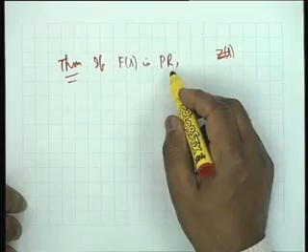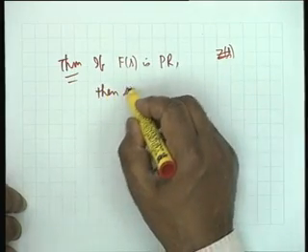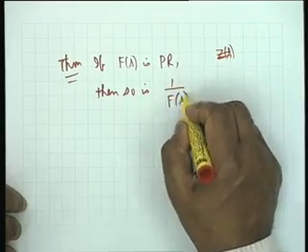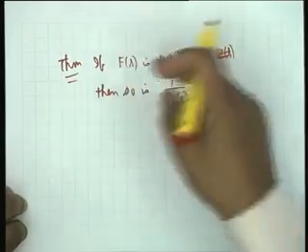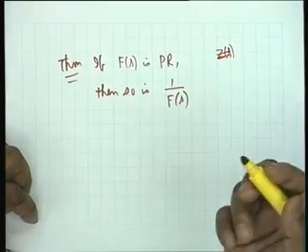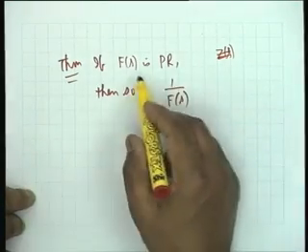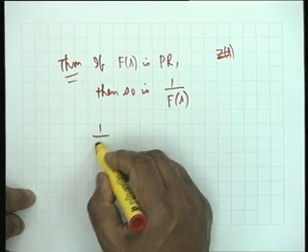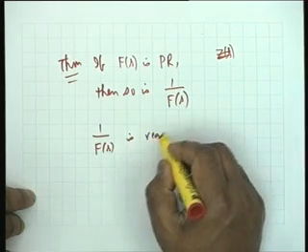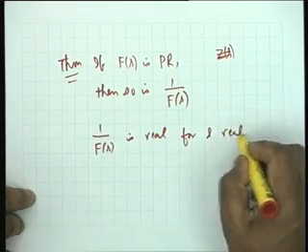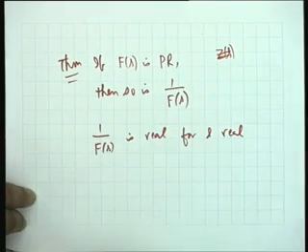All right. As I said, Z of S, the driving point impedance function, is positive real. We want to extend it to the driving point admittance function, and all that is needed is to prove this theorem: if f of S is PR, then so is 1 by f of S. That is, if the impedance is PR, then the admittance is also PR, and it's extremely simple to prove. If f of S is PR, then obviously 1 by f of S is real for S real. Agree? Because f of S is real for S real.